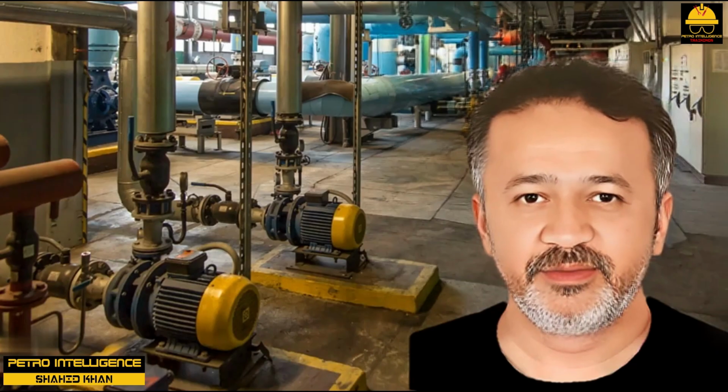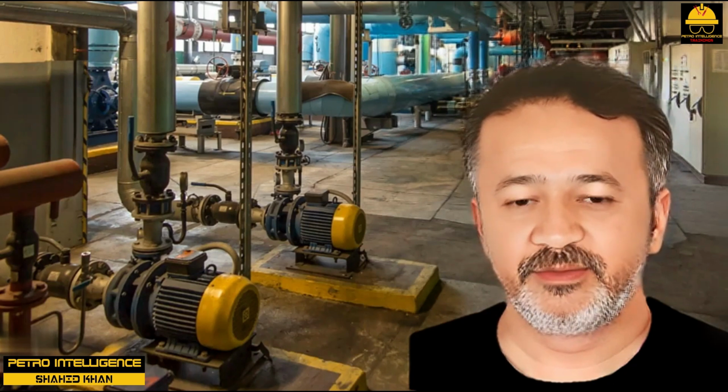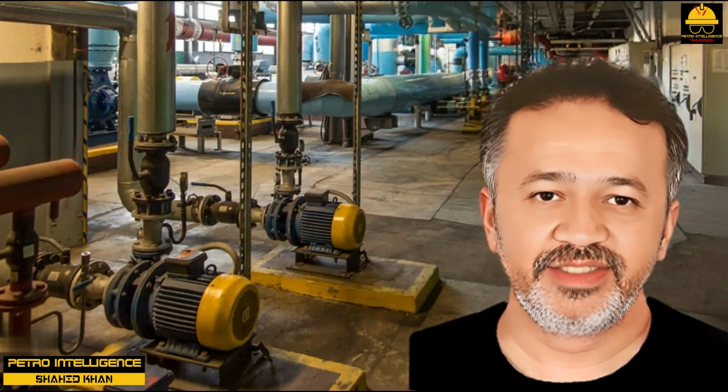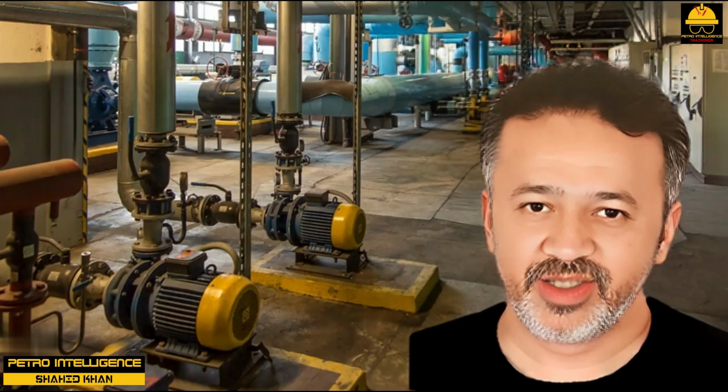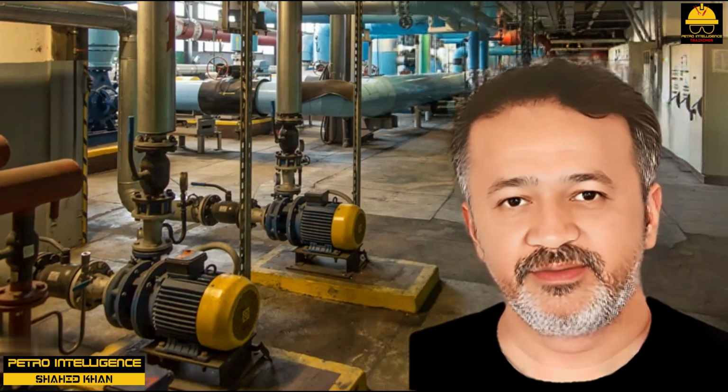Increasing the size of steam nozzles. Many steam turbines do not have full-ported steam nozzles. The existing steam nozzles may then be exchanged for larger nozzles. An increase of nozzle diameter of 10% would increase the turbine horsepower by 20%.